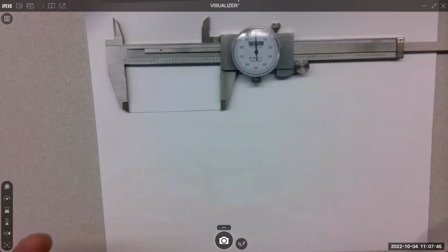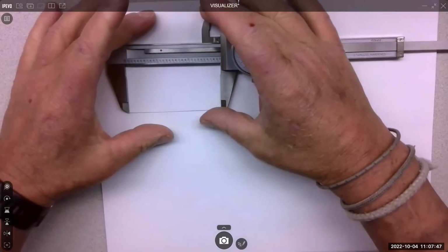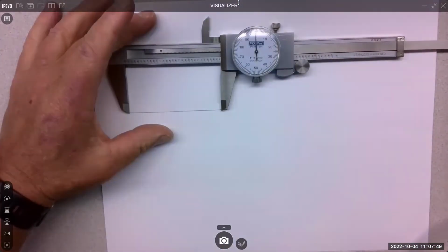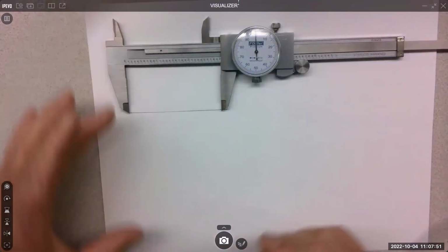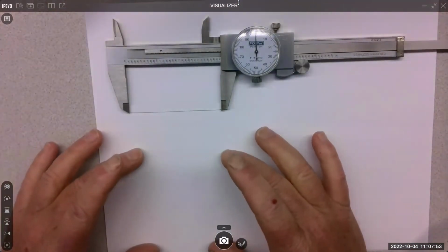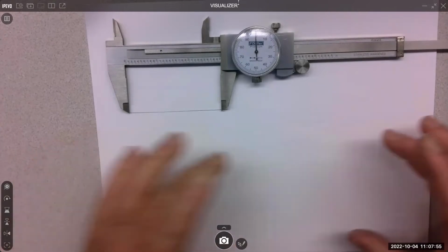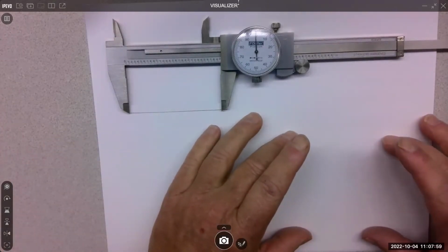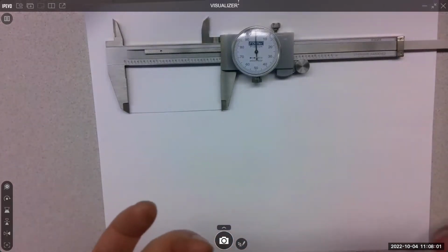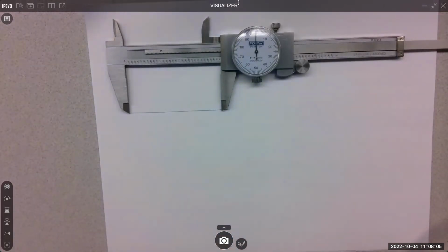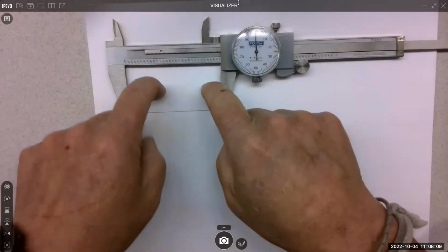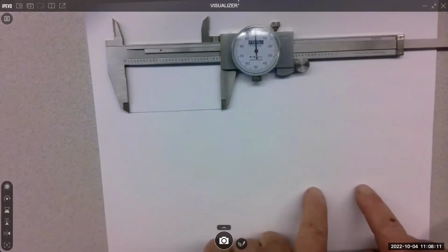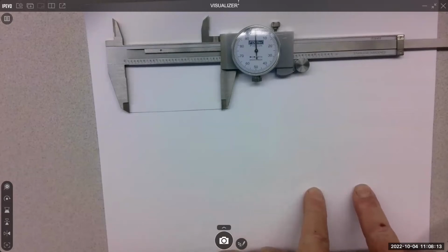And our drawing layout is top view. Since we've defined the top view, the front view will be here below the top view, and then the right side view will be here: front, top, side. Very standard, what we call orthographic layout. Ortho meaning 90 degrees. Each view is 90 degrees from each other. So top view, front view, side view. Very typical. They're called the primary views.